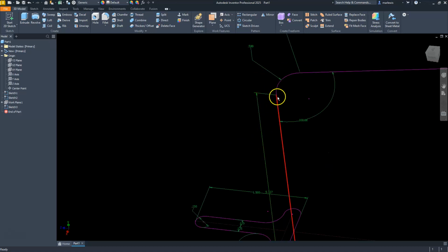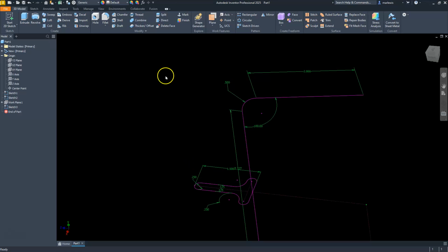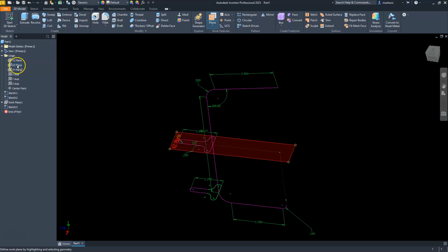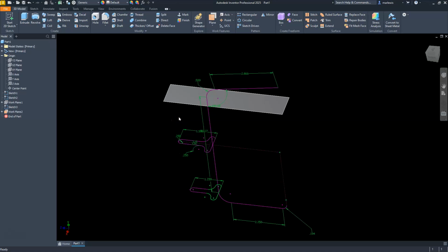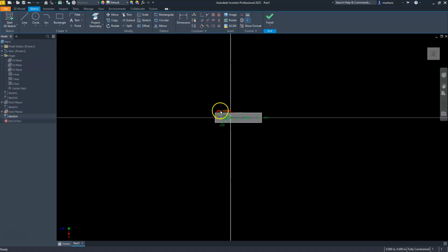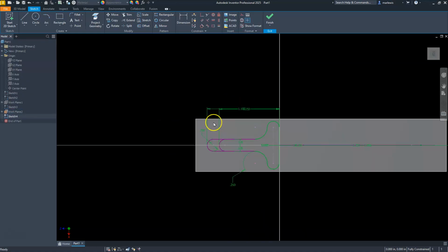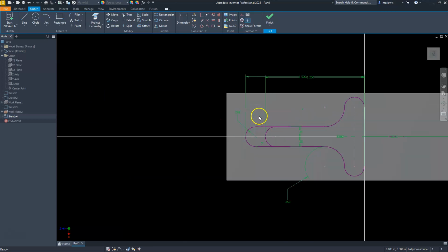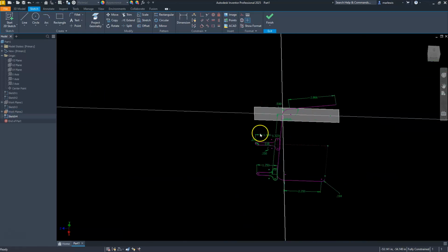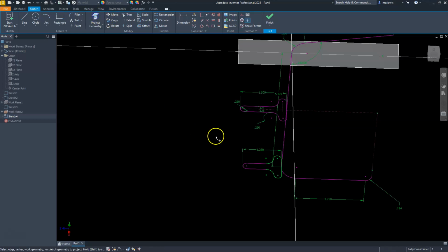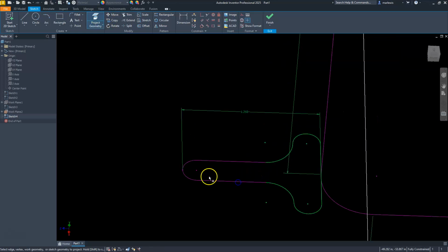Okay, let's put another plane up here at the top. So I'll go back to plane. Go find the plane that I want to copy, which is going to be this XY plane, and then I'll select that endpoint here. Let's select that plane, then select create a sketch on it. On this one, I will leave it sideways since it's the exact same size as the other one. So let's rotate this up. Let's use our project geometry, and then select all around this shape here.